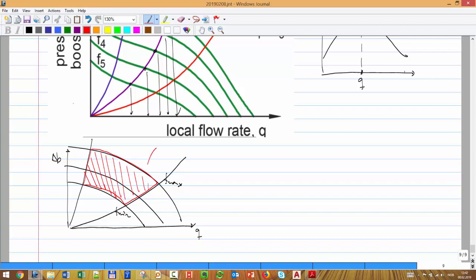That's the feasible operational area of the pump. Your points have to be within that range. And if they can be as close as possible to this best efficiency line, that's best. That's the pump designer. They try to select a pump where the line passes through all of your points, which is a very challenging task.